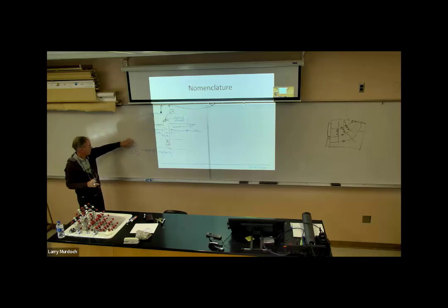And so the flow rate, if we're pumping at a constant rate and we pump this well long enough so that we reach steady conditions, which doesn't always happen, but if it does, then the drawdown is now steady. And this is then a constant. It is one of the measures that's used to describe the performance of a well.